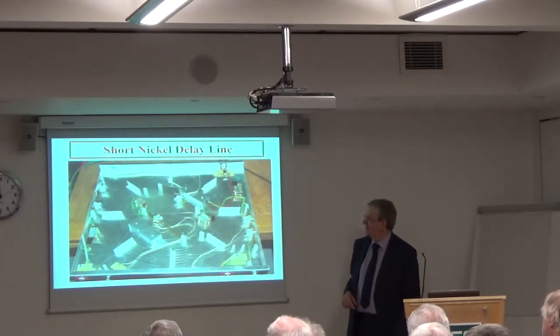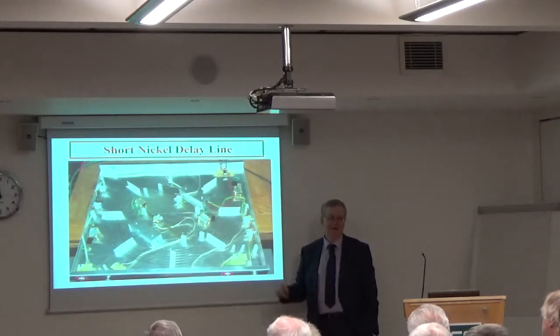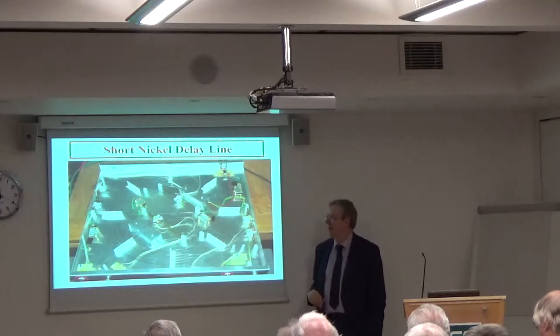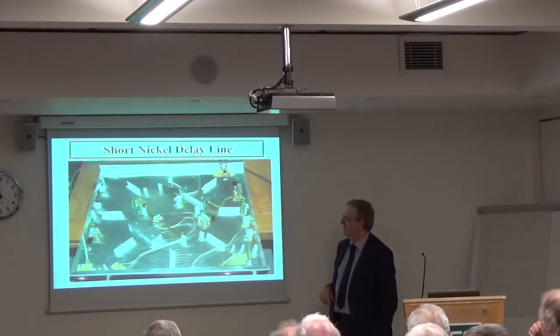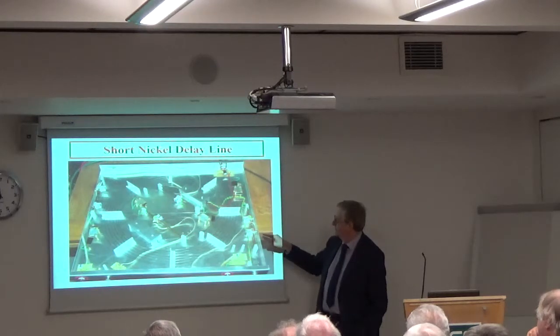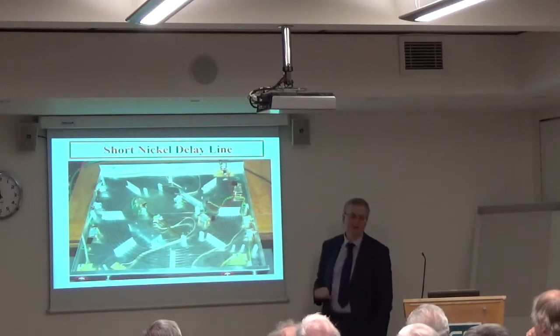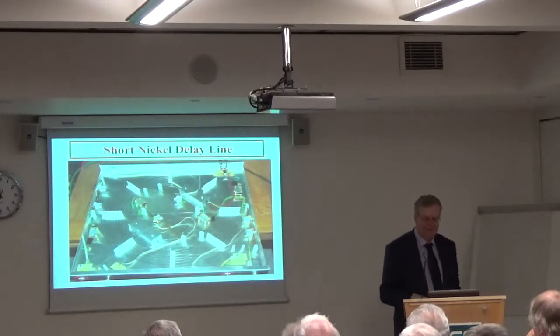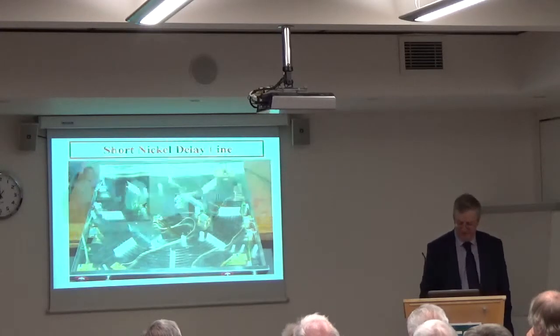A huge amount of research, starting with what's the wire made of, how do you support it, how do you coil it without introducing attenuations and reflections and so forth. How do you make the little fingers that put the twist into the wire to send the ones and zeros through? How do you roll those to the wire without eating all the way through the wire and so forth? A fascinating sub-project in its own right.